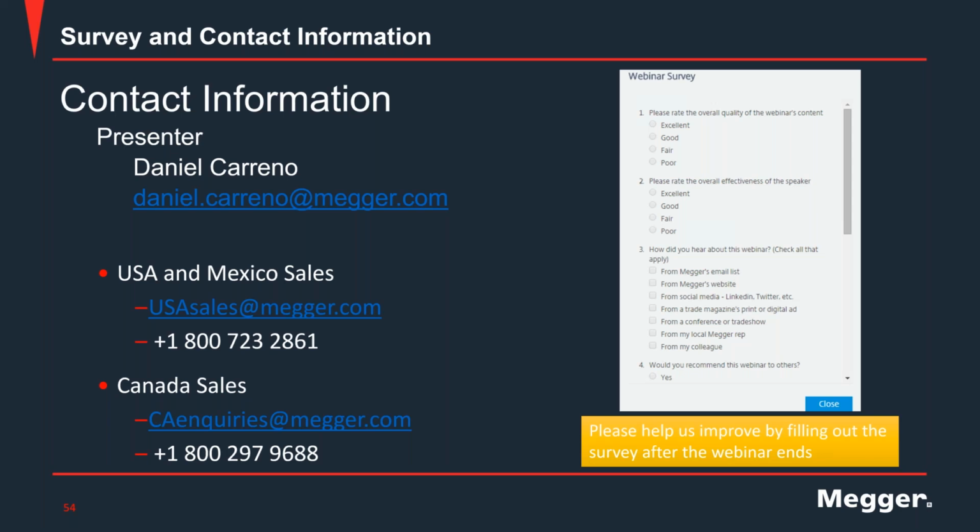Besides that, if you did the testing in the right manner and still the value is high, then there's something wrong with the transformer, and it needs to be investigated. It may be that the transformer is designed in that manner, but again, like I said, the standard says that 0.5% is the limit for transformers.